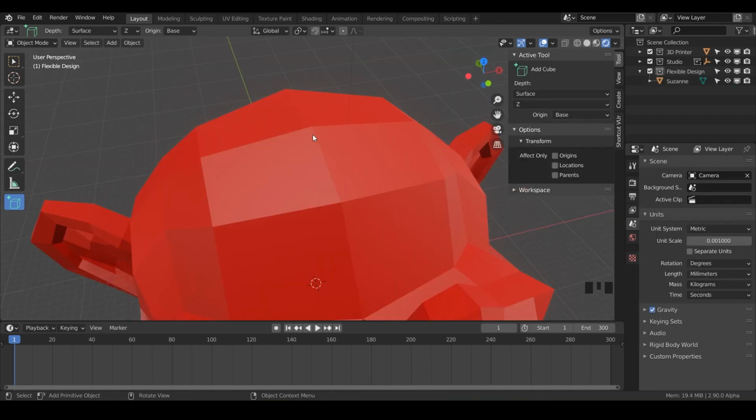Another cool thing is if you hold Control, it'll turn on the snapping. So notice I can snap to these little origins right here. This little circle appears when I hold Control. So I can hold Control, click and drag, and then press Alt. And Alt switches you into center mode right there. Or I can let go of Alt, and now I'm back into base mode.